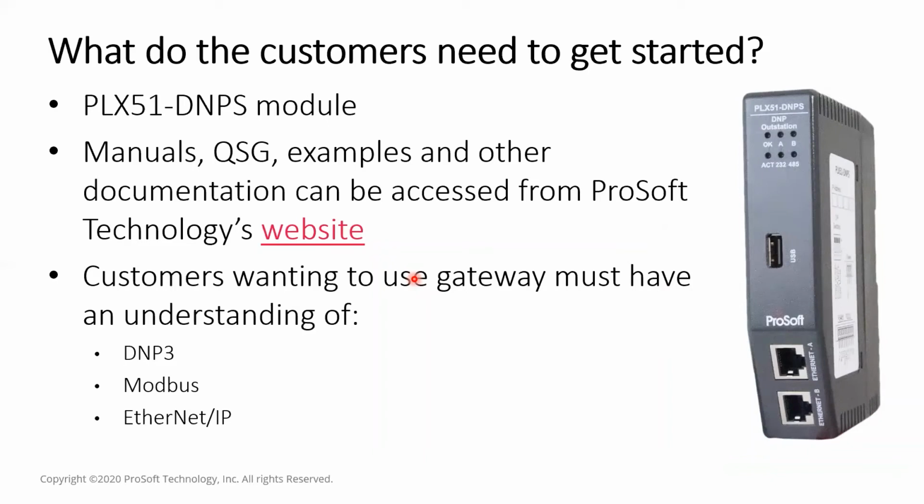As with all of our products, if you go to our website, it is very user-friendly. You have all of the information in there, whether you're looking for manuals, whether you're looking for the configuration software, which is free, by the way, whether you're looking for frequently asked questions, the data sheet, architecture diagrams, it's all available on our website that you can go ahead and download. And customers wanting to use this gateway really need to have at least a basic understanding of what DNP3 is, and also understand some of the other industrial protocols, including Modbus and Ethernet IP.